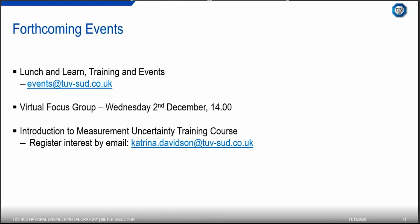The first question is, what do you believe the main challenges are in uncertainty analysis? I would probably say three. First, making sure that you consider all of the uncertainty sources that may be contributing, so what environmental effects are having, and for instrumentation, looking at drift, what the calibration uncertainty is, what the resolution uncertainty is, and other factors.